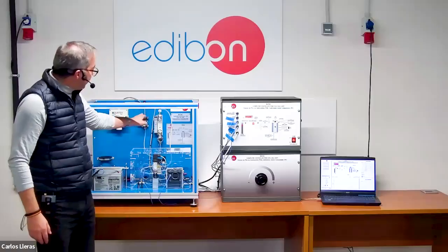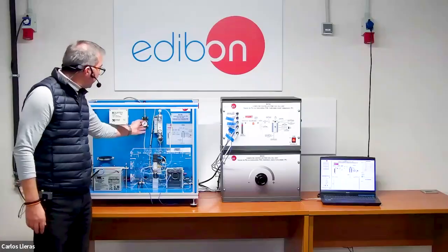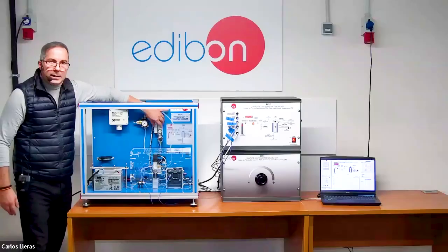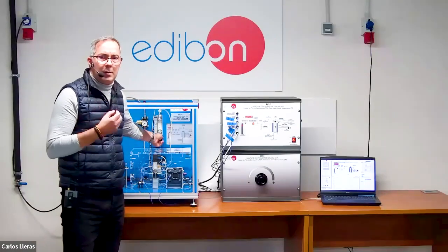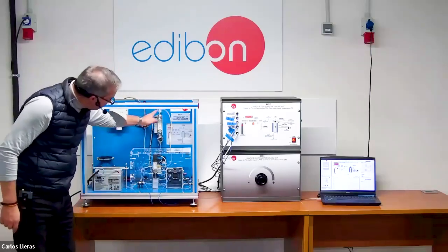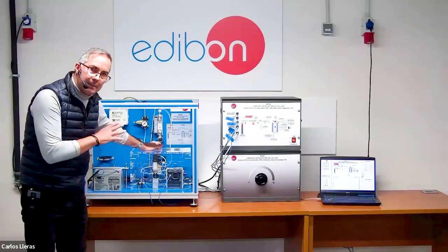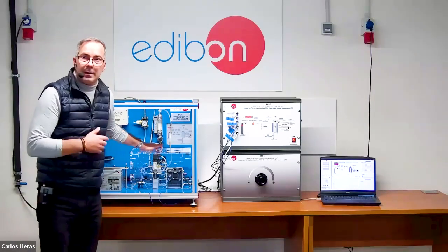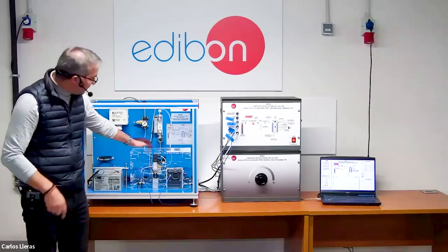That oxygen, I'm sorry, not oxygen, that hydrogen that is coming in will go through a pressure regulator. Okay, so we have a pressure regulator here that will go through a flow meter, which is located right here on the top, and that can also be regulated. We can regulate the flow of the hydrogen that is going into the system. Okay, if we follow this pipe, we're going to make a close up for you to see this from a closer position. This is a solenoid valve that will open and close accordingly, depending on whether you want to shut the system or leave it open.